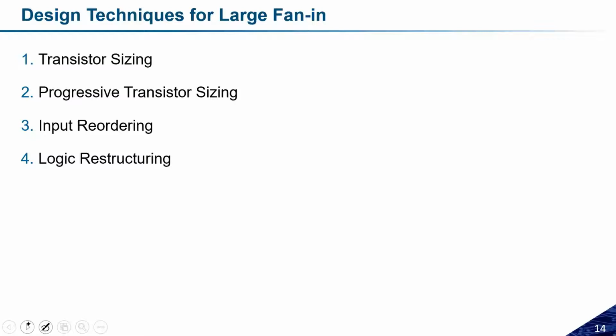What is transistor sizing? Before I explain transistor sizing, let me go back to some previous concept which we have already studied. We know that if I am increasing the size of any transistor, like if I am increasing the width of any transistor, the equivalent resistance or the on resistance will reduce. Okay, so suppose I have to reduce the delay.